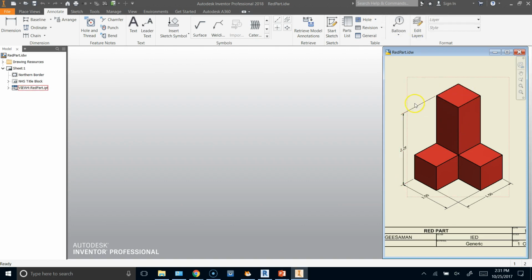So essentially, this rectangle in here is going to be removed material. This rectangle over here will be removed material. And I'm going to do this by making what's called a cut extrude instead of an additive extrude. At this point, we've been making add extrudes or join extrudes. We're going to use a cut extrude.